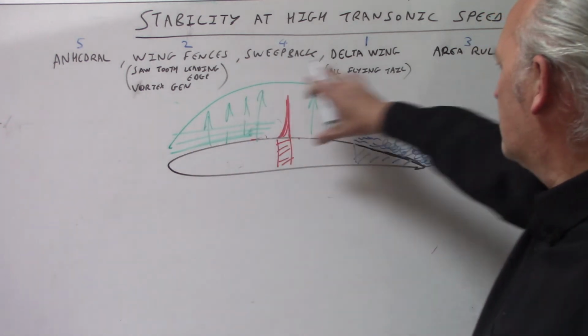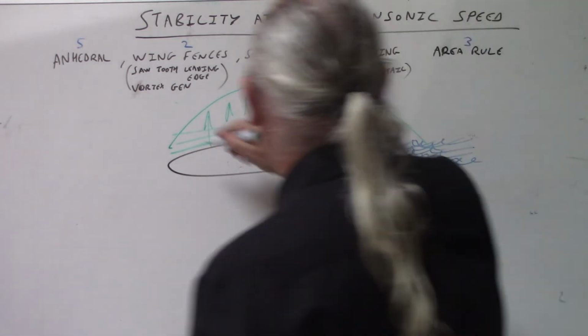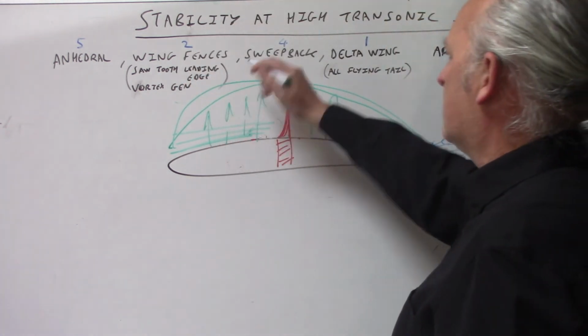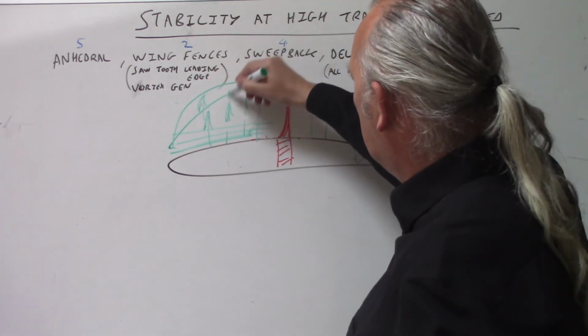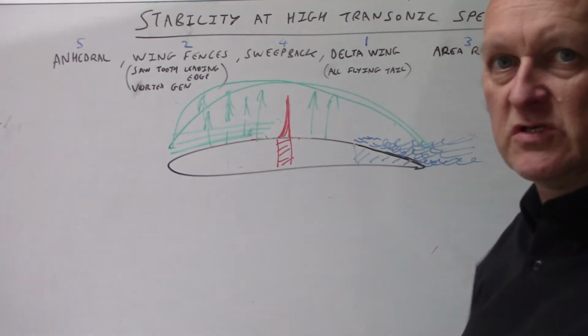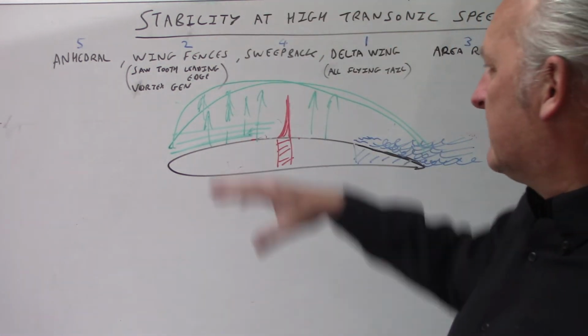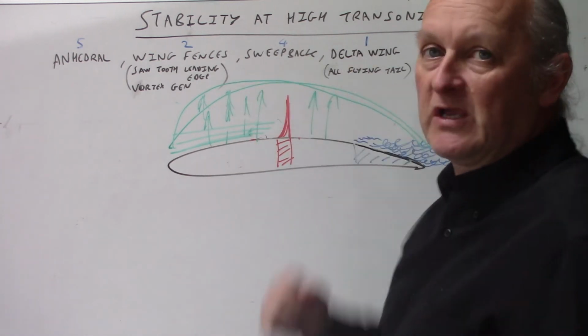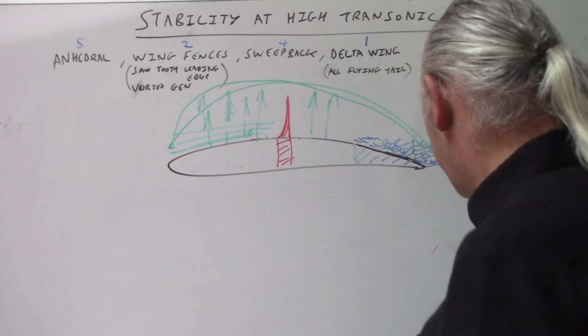You have this kind of pressure around the wing. It won't look like that. It'll probably be more of a bump like that really, and that's how the pressure's dissipated around the wing. That's where your lift is, okay? It's your bubble of lift. That's the difference in pressure above and below the wing. That difference in pressure is sucking the wing into the air, according to Bernoulli's theorem.